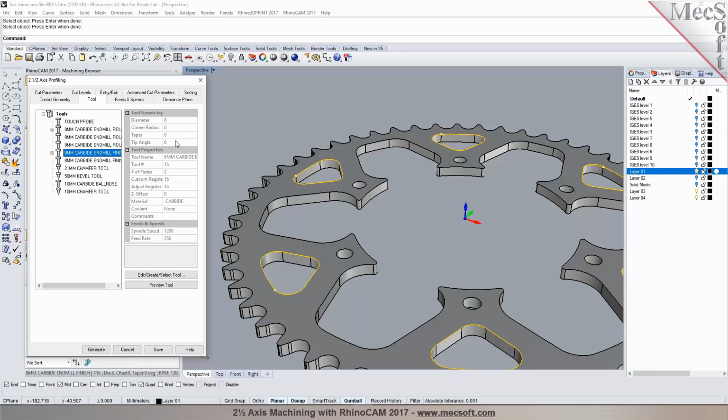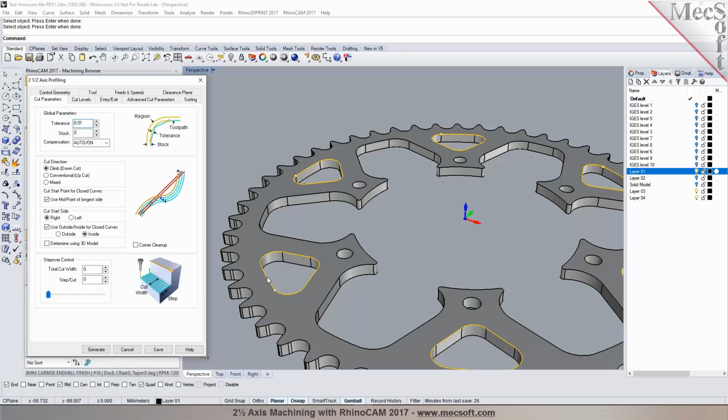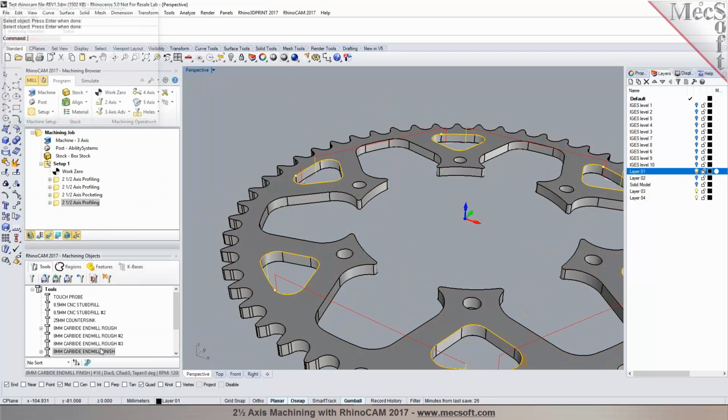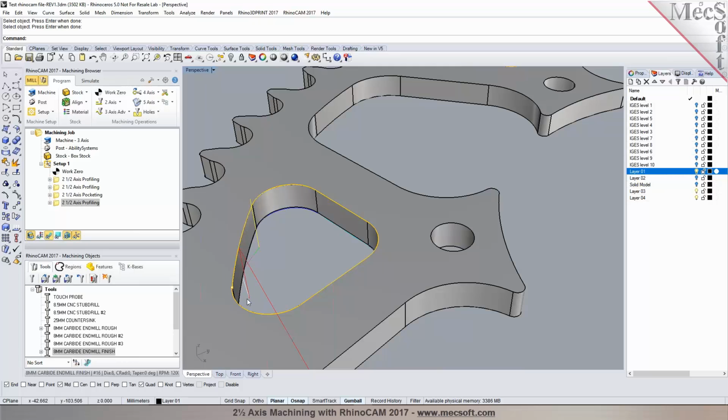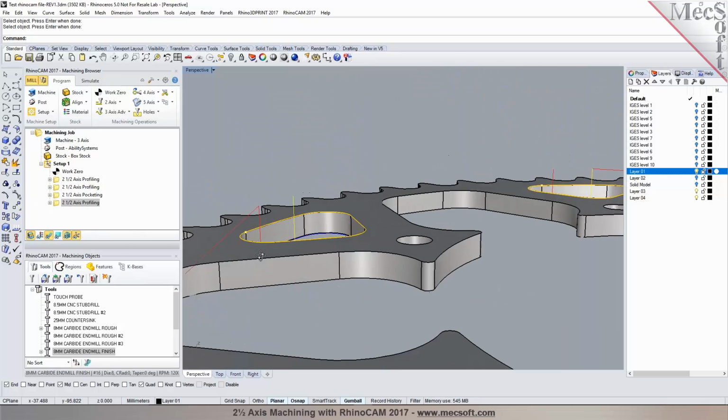Now, if you need to program it on the geometry itself, like a centerline cut, the way you would have to do it is in the cut parameters, you have stock to leave, and you would need to specify this value equal to your tool radius. In this case, that would be -4 millimeters. So when you generate it, it'll actually put the tool path back on the geometry. However, this is going to invalidate the simulation, but then you would be compensating for the full diameter of the cutter at the machine. Right. So you can't simulate it and generate the...